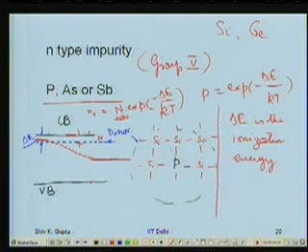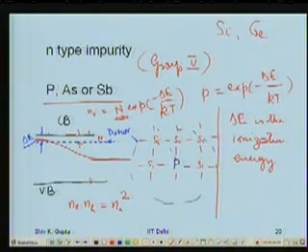Now there will be some holes produced, and those electrons can also get excited in the course of time. In other words, there will be some holes in the valence band too. The law of mass action provides us that the number of electrons in the conduction band times the number of holes in the valence band is equal to the square of the intrinsic charge carriers at that temperature, whatever this number.